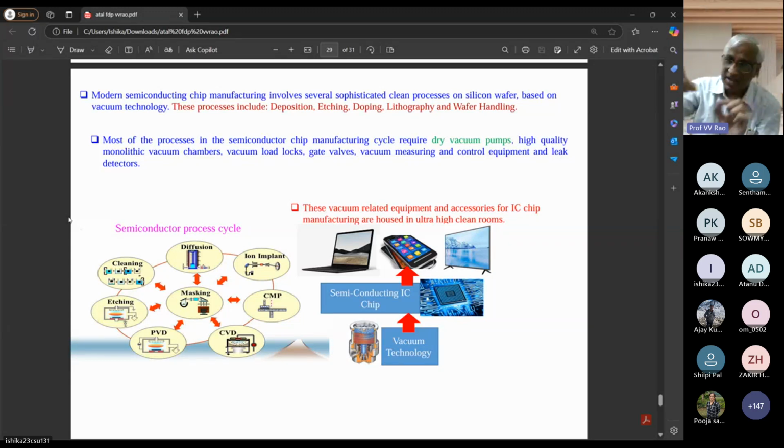All that will be one die. Several such dies are there on a single wafer, and you have to cut these things with a laser cutting very carefully. Things have to be done under vacuum. Before that, pre-checking has to be done. Till now, we have not done metallization. Then you have to make metal contact right from the bottommost. You have to have some holes.